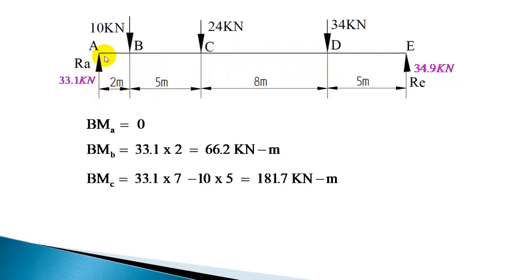It's not the direction of force which is producing a positive bending or negative bending. It is because left side forces we are considering, and with respect to this, downward force is producing negative bending moment and upward force is producing a positive bending moment. So that way upward force will have positive shear force and positive bending moment. Downward force will produce negative shear force and negative bending with respect to any section. So that is applicable only when you consider the left side portion.